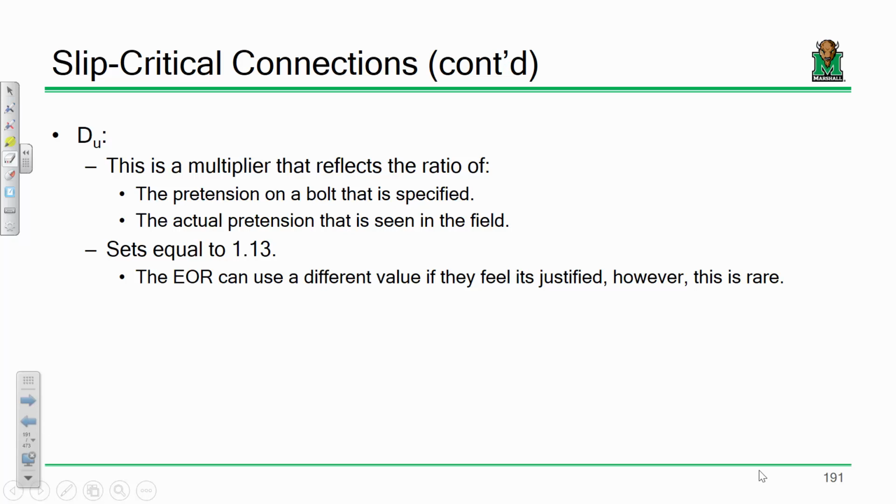And when we talk about safety, keep in mind, you're not using raw loads. You're taking your dead load and upping it by 20%. You're taking your live load and upping it by 60%. So there's a lot of safety built into the spec, right? That's why we do 1.2 dead plus 1.6 live. If you have an element that has 100 kips in live load, we're saying design it for 160. That's a big deal, so that would be a really valid point to mention. Does that make sense? Is everybody else okay with that?